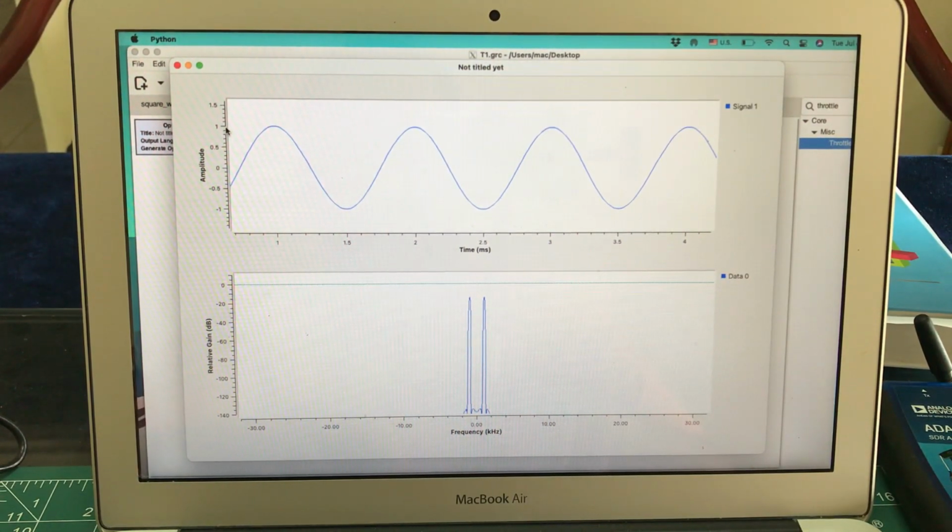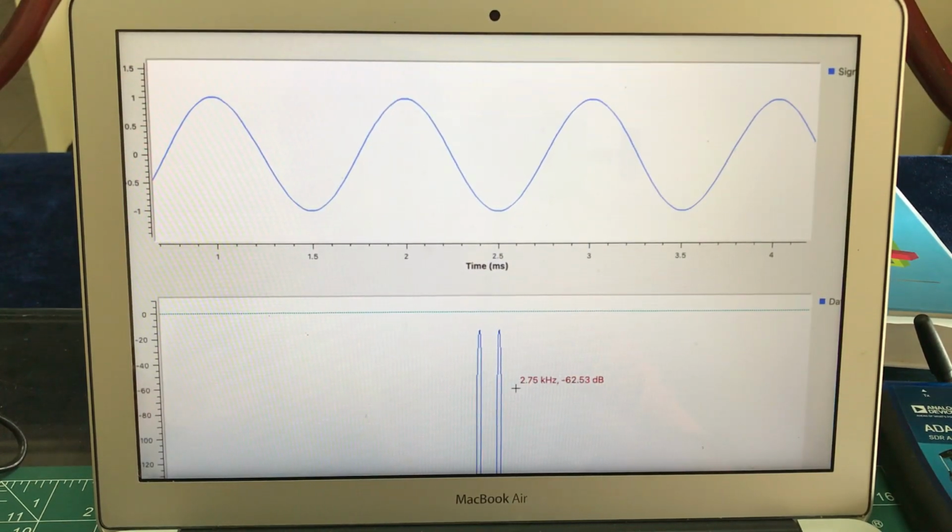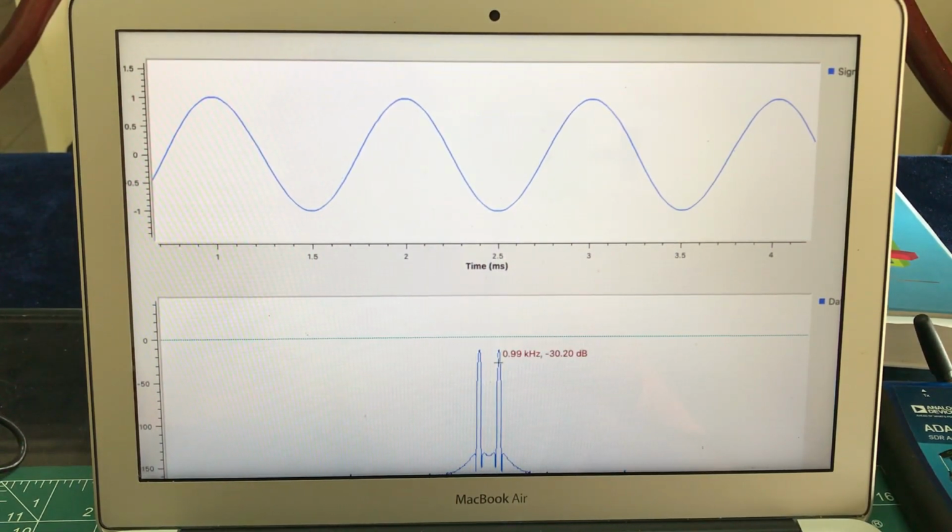So as you can see, this is definitely a cosinusoidal signal, starting off at 1 and going all the way up to 1. When I look at the Fourier transform of this signal in my spectrum analyzer, this is what I would see: that indeed I do have a 1 kilohertz signal. The spike is at 1 kilohertz. So this signal is around 1 kilohertz.